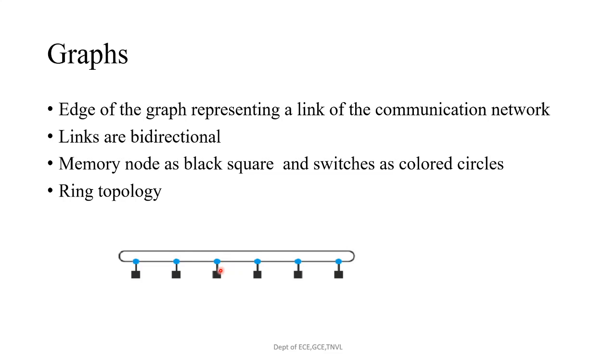The first network that connects a sequence of nodes together, which we are seeing here, is a topology called a ring. Since some nodes are not directly connected, some messages will have to hop along intermediate nodes until they arrive at the final destination. Unlike a bus, a shared set of wires that allows broadcasting to all the connected devices, this ring is capable of many simultaneous transfers.